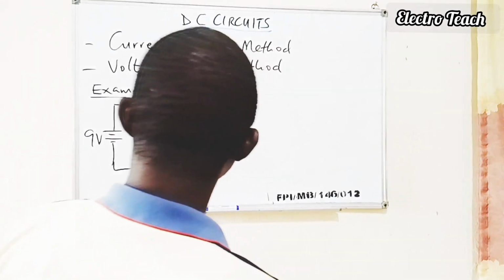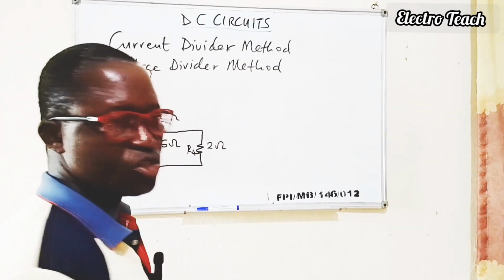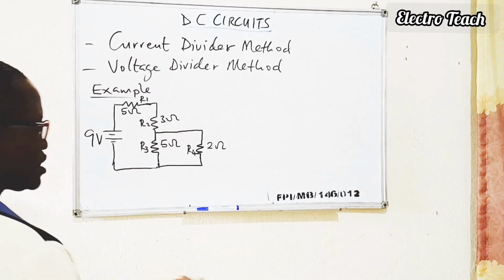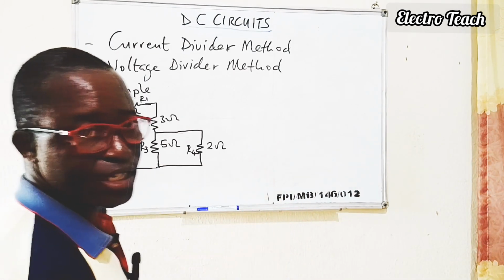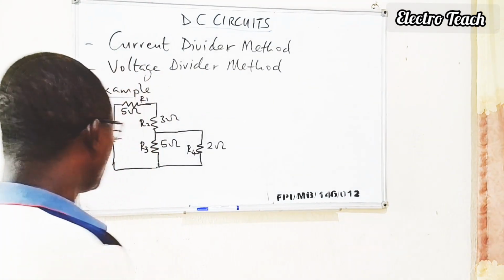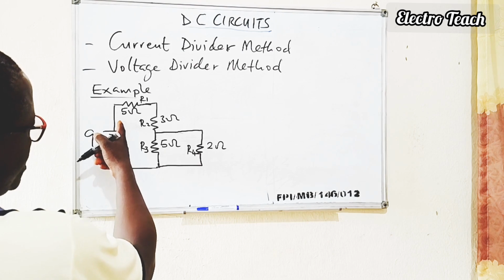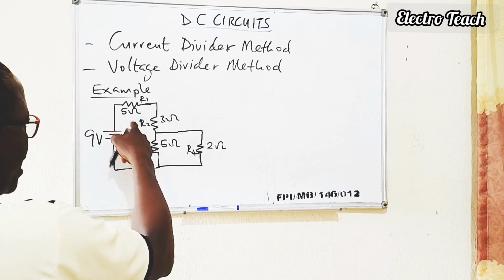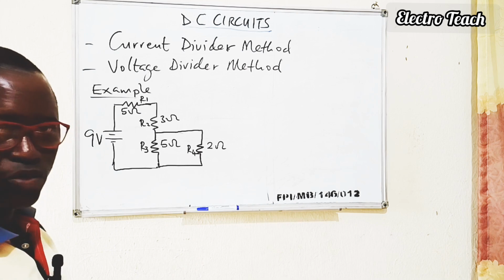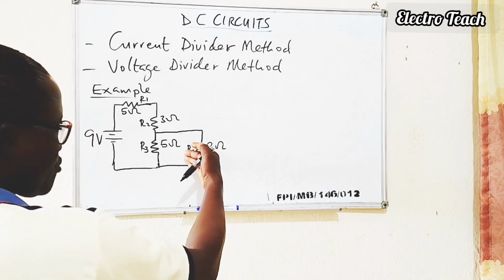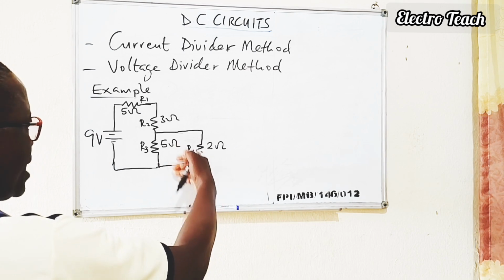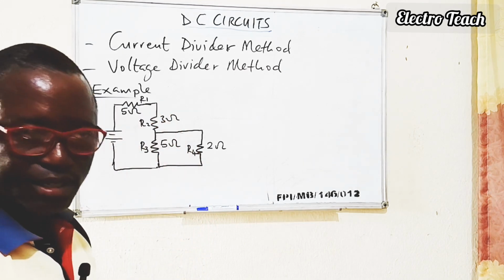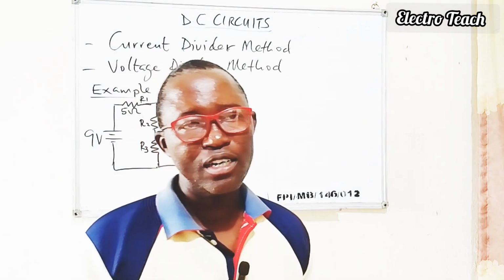All right. Now, the first thing to do is to determine the total equivalent resistance in the entire network. And to start, you usually start from the right-hand side of a network like this. You cannot begin from here, because if you begin from here, you may not be able to determine the relationship between these parts of the circuit and these other parts of the circuit. But to simplify the circuit, you start from your right-hand side and then you begin to minimize it, reduce the combination of resistances towards the left-hand side until you get the total equivalent resistance.